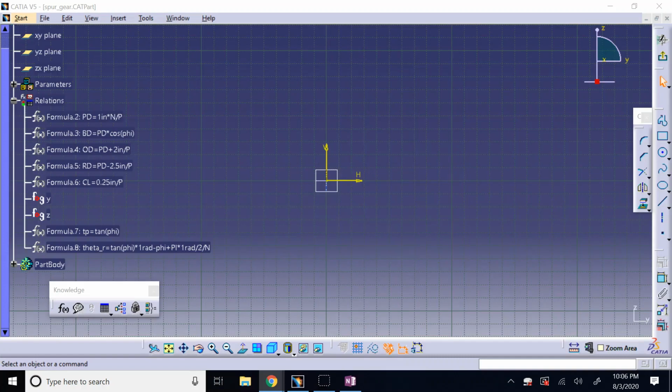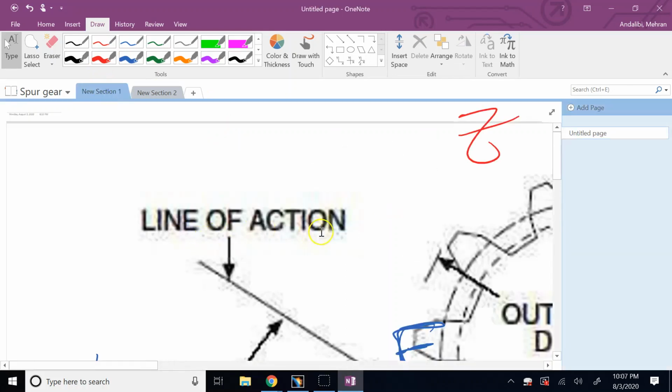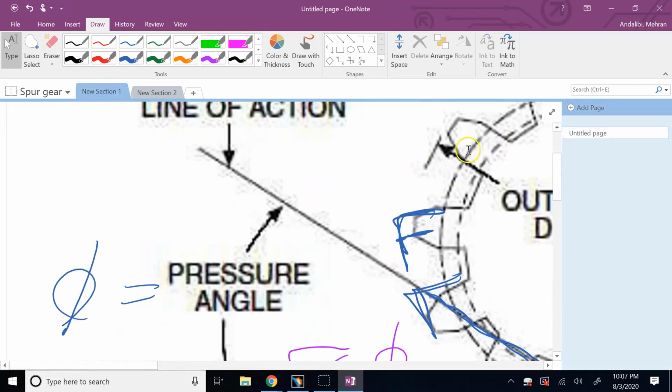Now let me create the involute curve for you. Evaluate, connect them with spline, mirror it, trim it, and create one tooth profile. Once you create one tooth profile on page 14, the rest of it is nothing important, okay? So first, it asks you to put all of the points for the involute curve, because what you do is you are going to evaluate those functions for y and z. You're going to evaluate them at a bunch of t points. So at some values of t, you evaluate them, you get a bunch of points, and then you use a spline and connect them together.